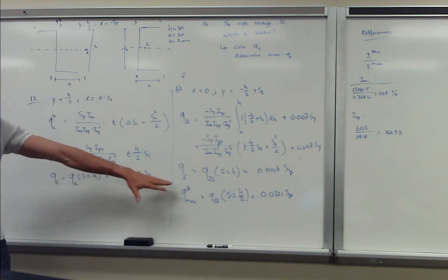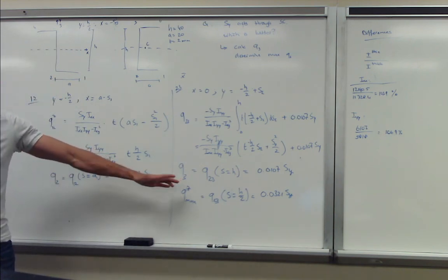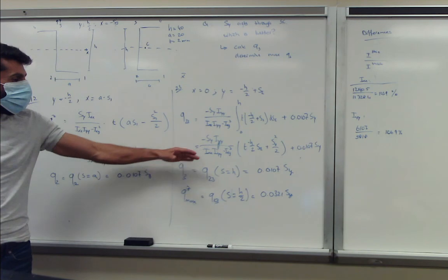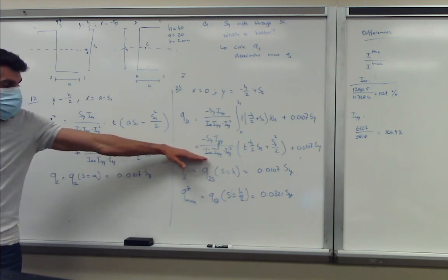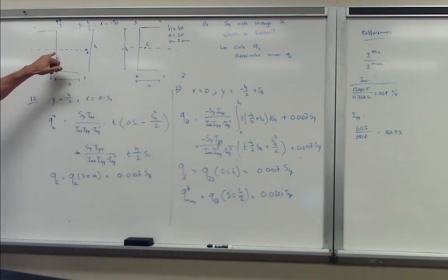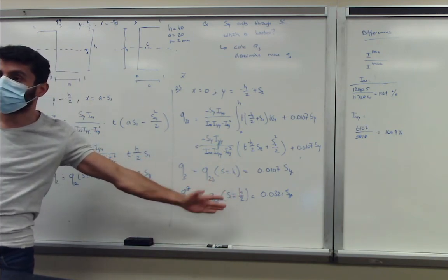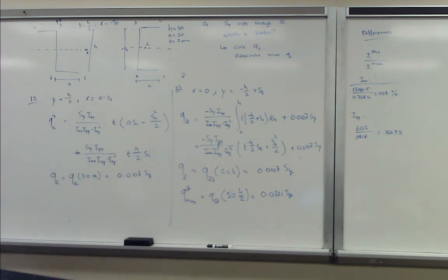And that's the reason why I said you don't have to calculate Q3, it's just to be complete. But the problem does not specifically ask for it. So you could have stopped at this point and said the maximum corresponds with our centroidal axis, so at H over 2 at segment 2, 3, how we calculated it. So you fill in H over 2 and that will be sufficient for this problem.